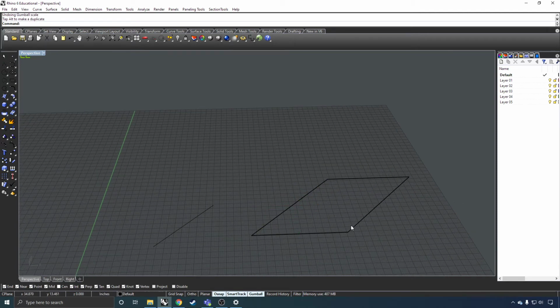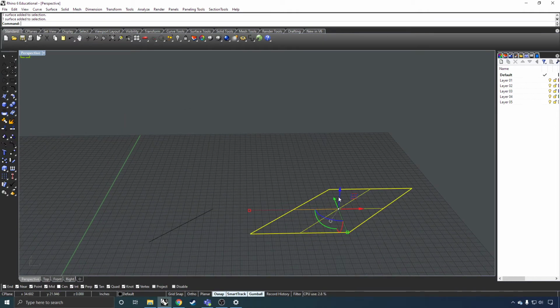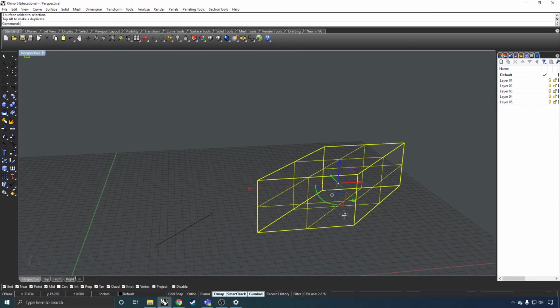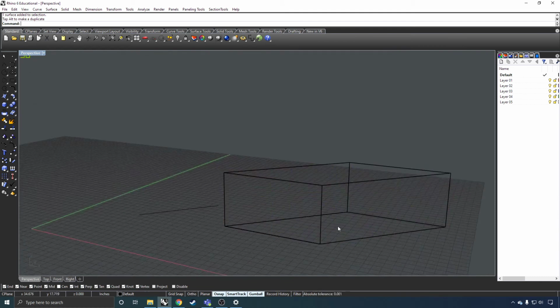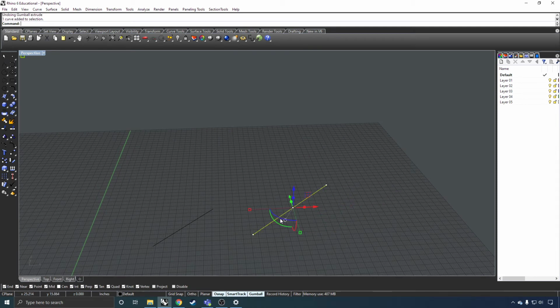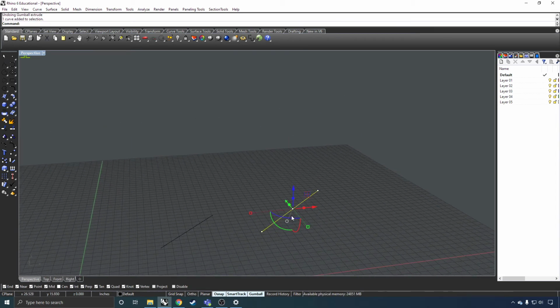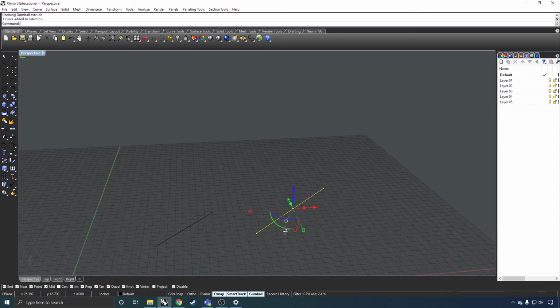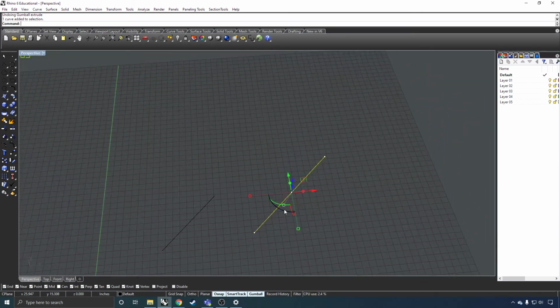So this is now a full shape, full surface. And if I extrude this upwards, it's a 3D object. We'll get into why you're not seeing shading and stuff on that in just a second. And if I go all the way back, you'll see that I have these couple of angles here, or these rotational degrees, and they do exactly that. They're just rotational. And you can hold things like Shift to lock them into the 90, 180, 270 degree positions as well.